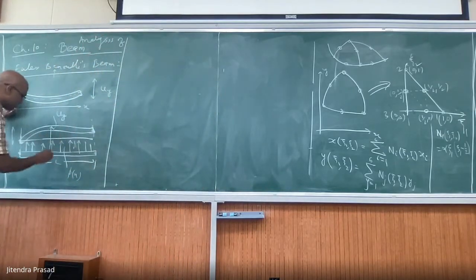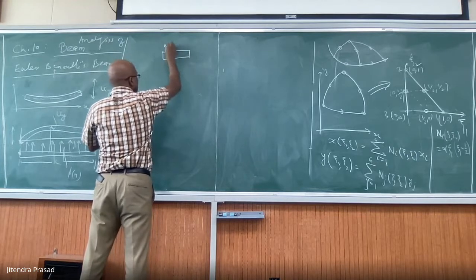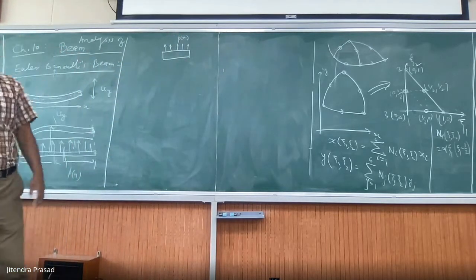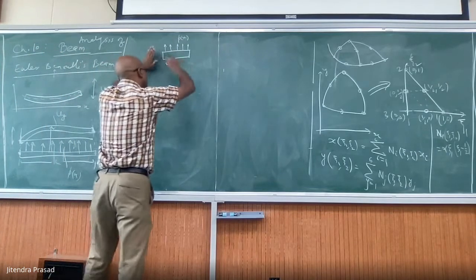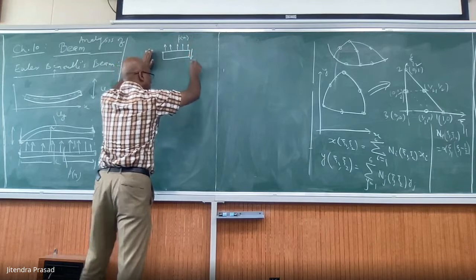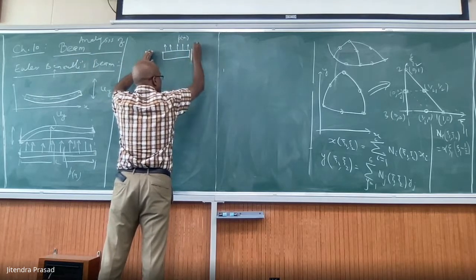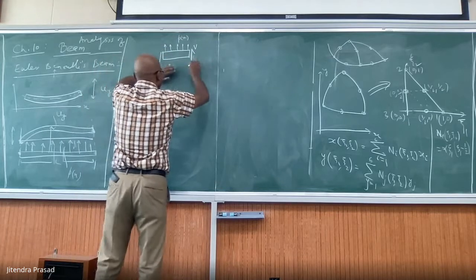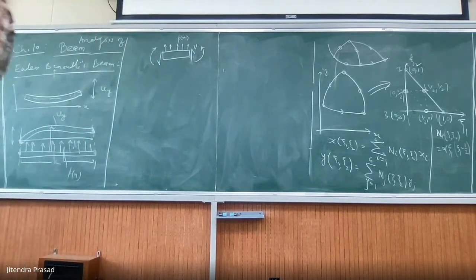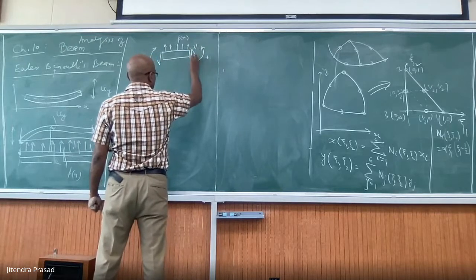Now, we will take a small section of that. So we have a small section. Of course, this has some pressure P(x), which is upward. And you know from our solid mechanics that it will have shear forces. Now, the convention there was, typically we wrote downward as a positive shear force, but here we will write this as V, which is upward. And then you have a bending moment, which is positive in the sagging direction, so this is positive, and V upward we are saying positive.